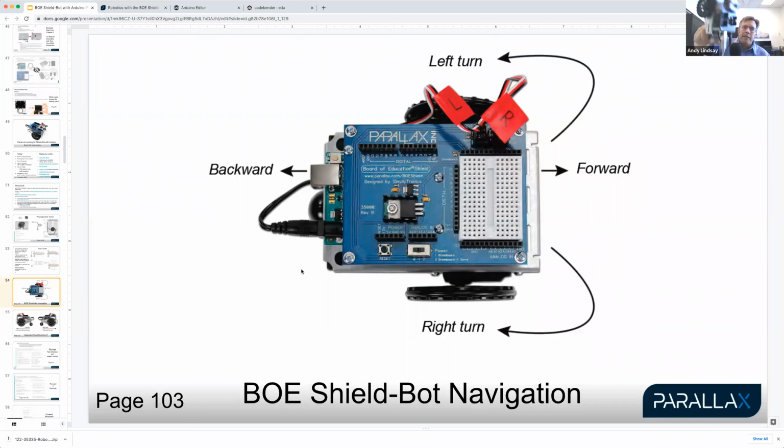Aside from that, in terms of connecting or disconnecting, there's no hard, fast rule for the order that you have to do it. So again, basically, if your robot's going to move with the 3-position switch in position 2, you always want to have the barrel jack or the barrel plug, which is this, connected to the barrel jack here.